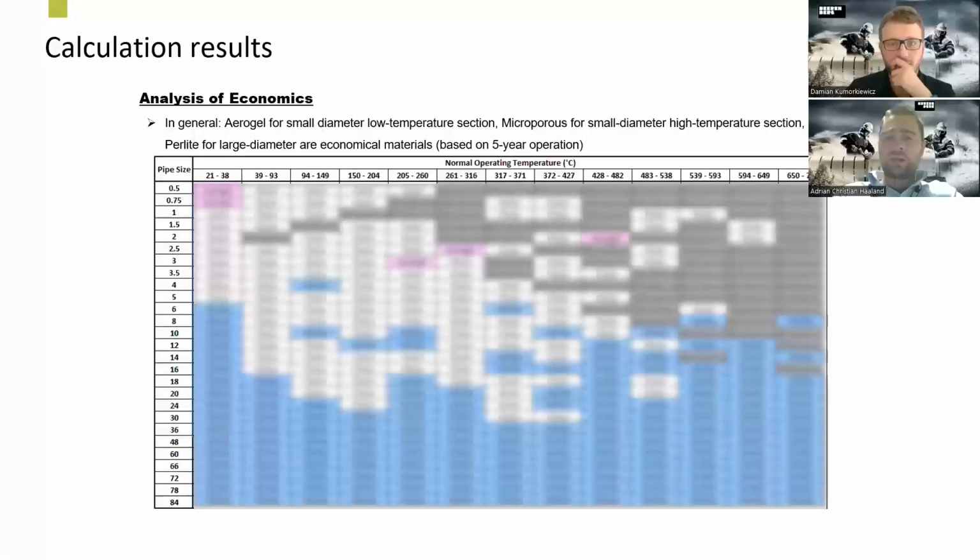But they had a lot of issues with CUI at the plant, and they know that it's better to assume a little bit too short a lifetime than to pay too much for the insulation system and put on a very conservative solution. So we used a conservative 5-year lifetime assumption.